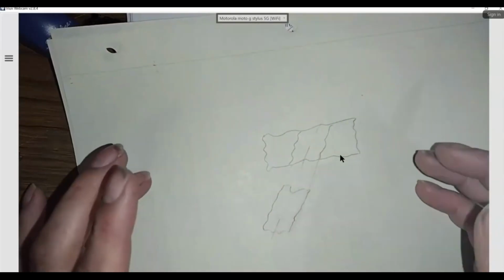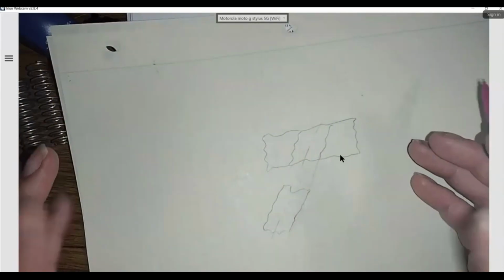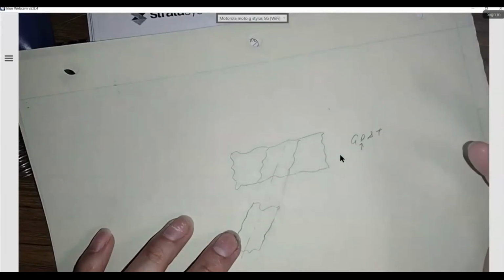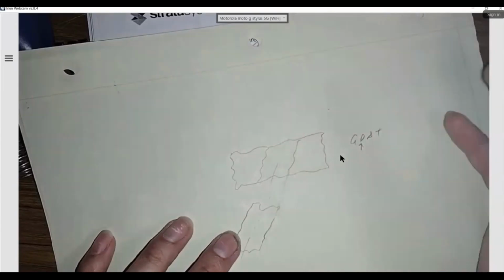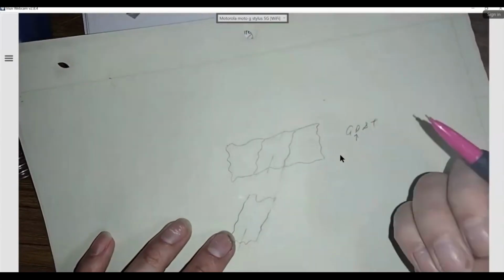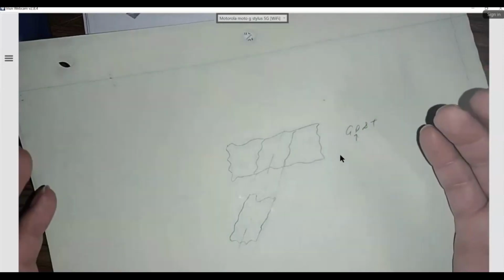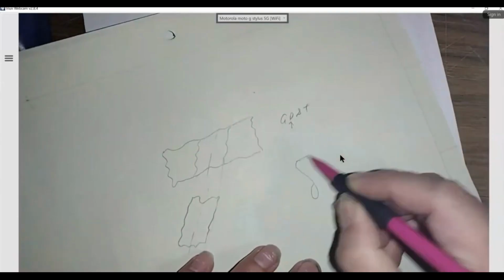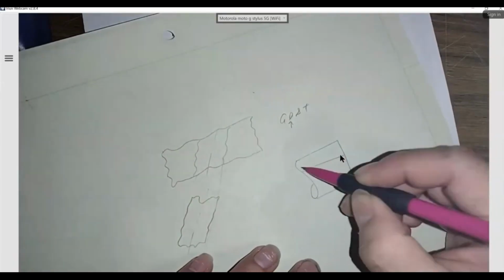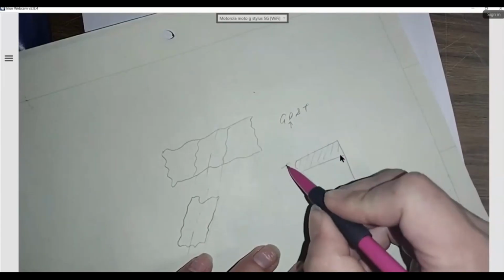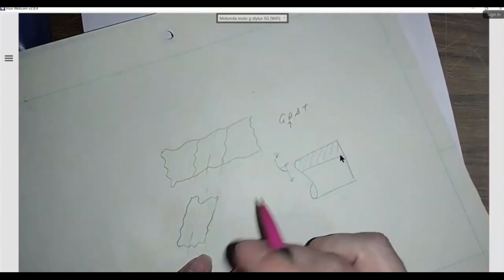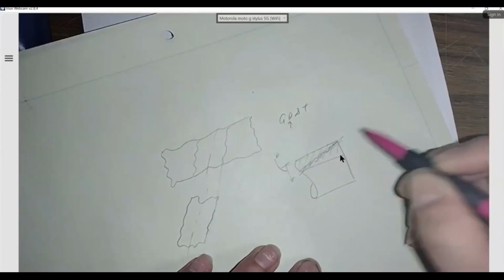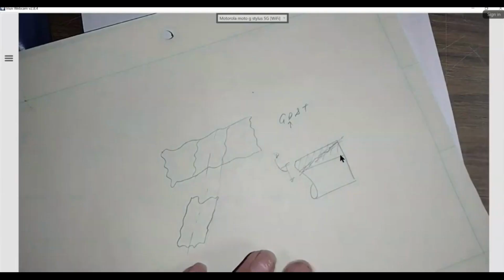Because the fit charts take care of your dimensional tolerance, which automatically controls the form. It has to live within the biggest I can get and the smallest I can get, and so your form will live within it. Does that make sense? I also have my GD&T form variations. This here will be my D for dimensional tolerances, and my form variations will live within it.